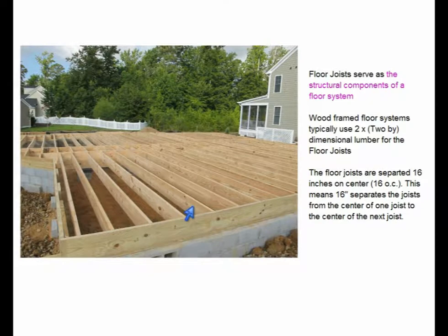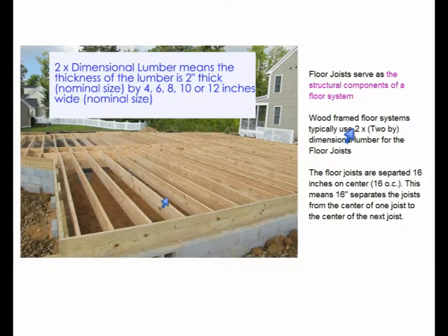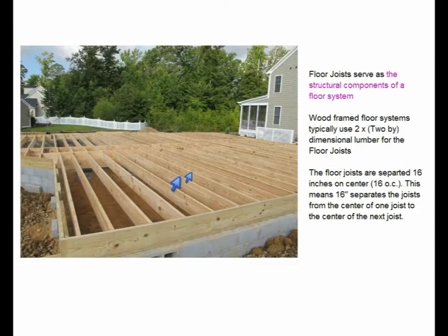They are typically made of what is called 2x dimensional lumber. These floor joists are separated by 16 inches on center. This means from the center of this joist to the center of this joist is 16 inches.